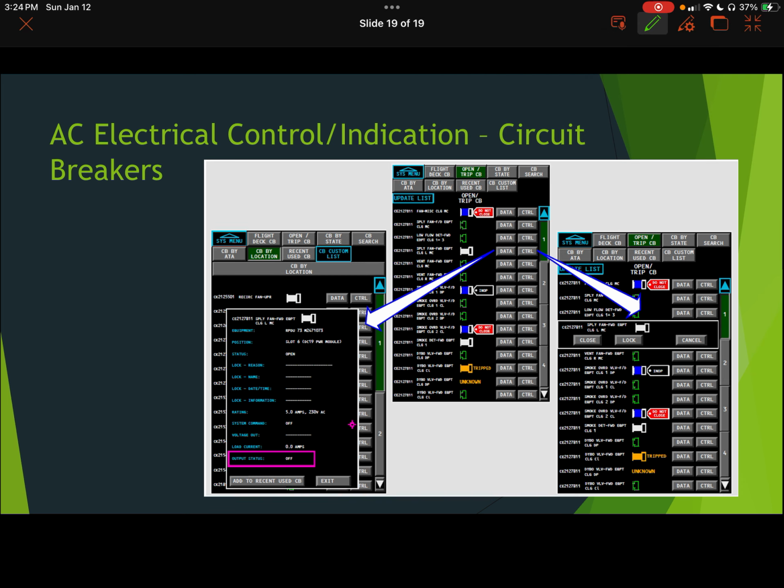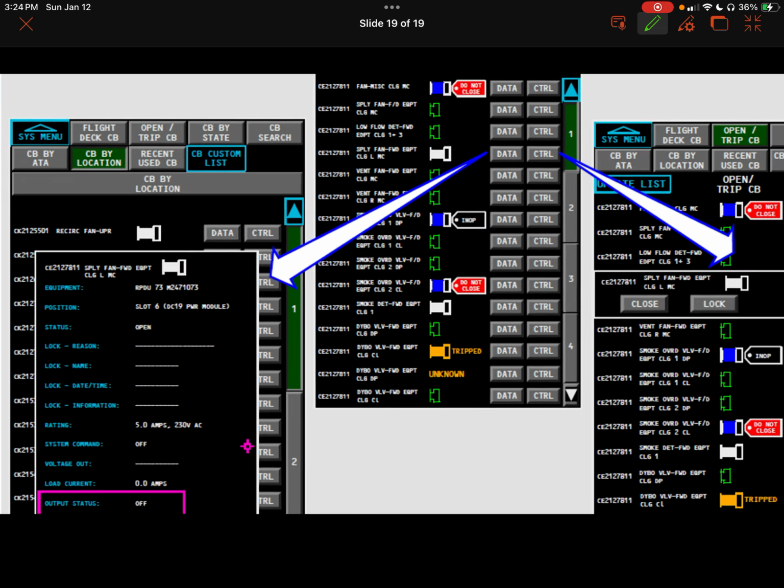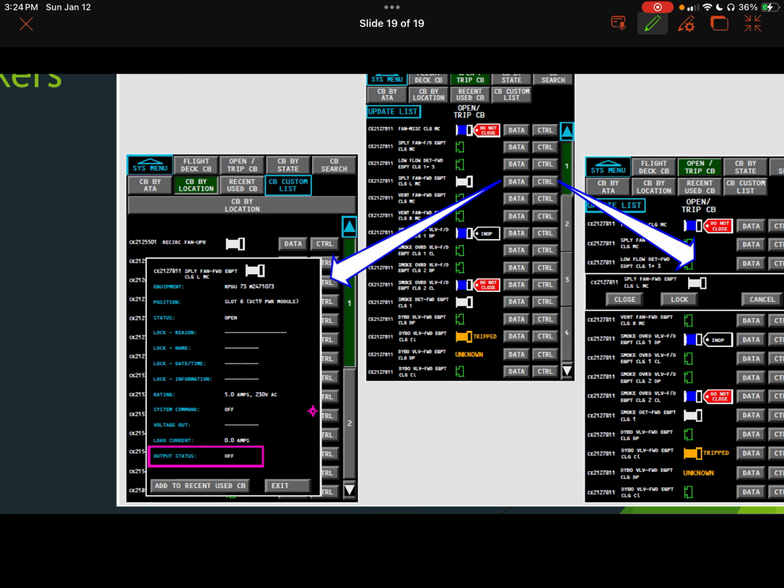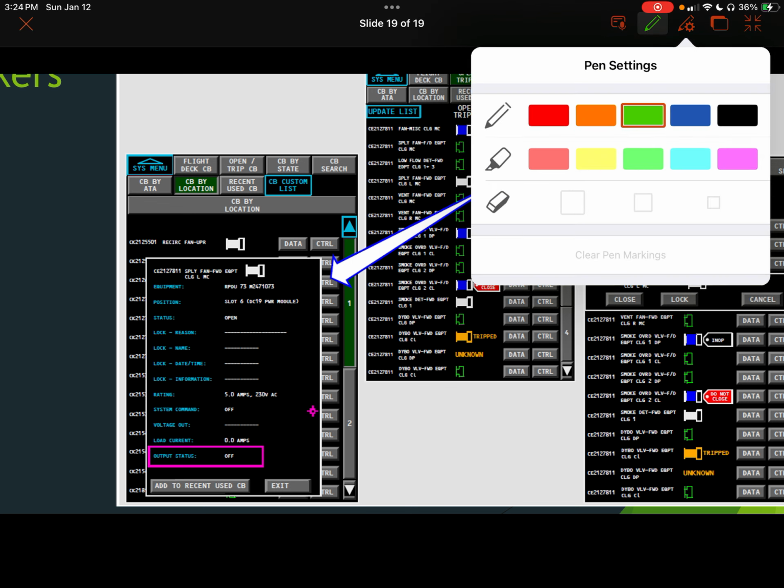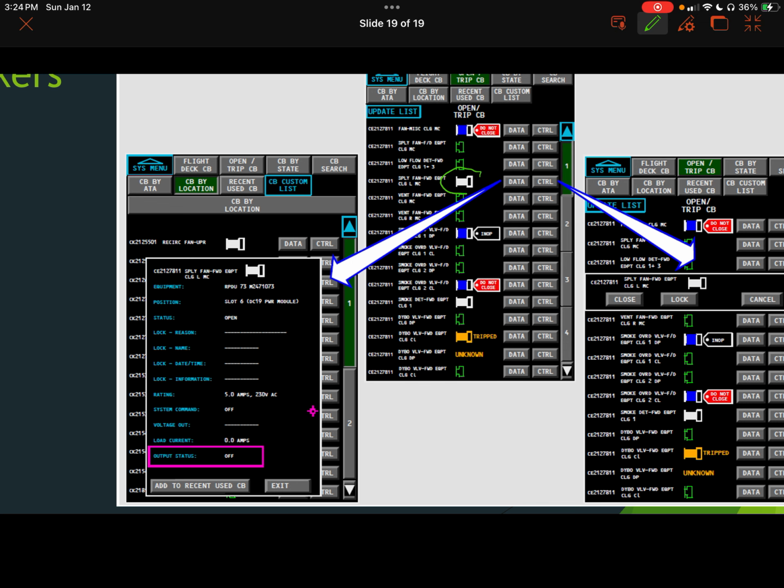Here's an example of what those remote control circuit breakers on something like an ICAS system look like. Again, this is that Embraer 175. I can blow this up a bit. The normal circuit breakers that are in green are the ones that are in the set position. And something where it's sticking out to the right and has turned white, that's a tripped position.